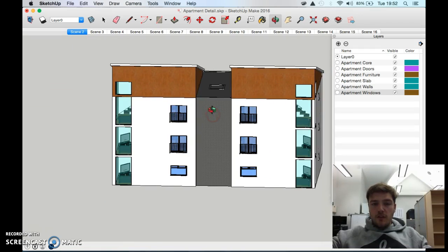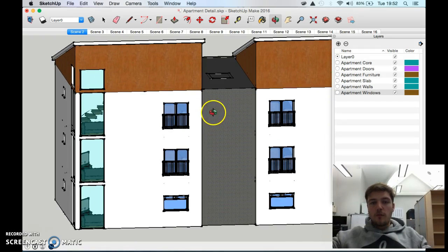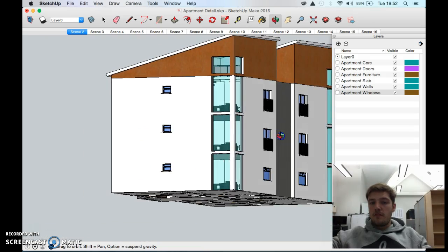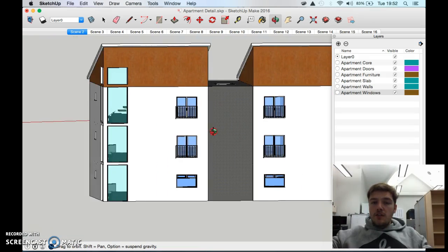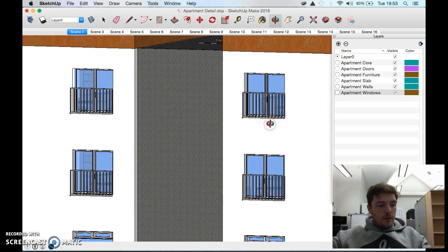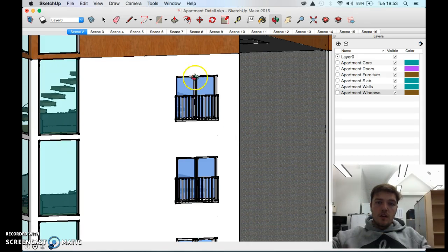The other thing I also noticed on the 2D drawing was that this was supposed to step back at the second floor level, so the rear wall was supposed to step back. I decided against that, mainly because I think it would look better from the outside if you didn't have a separate entity. I chose the windows to be the size that I did, mainly because I've spoken to a few window manufacturers and they told me standard sill heights and generally standard window heights, even though most windows can be designed to fit any space provided.